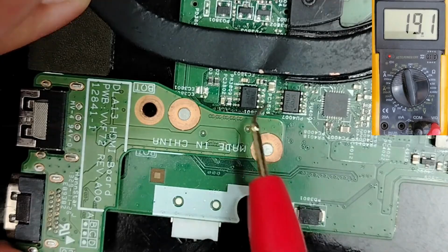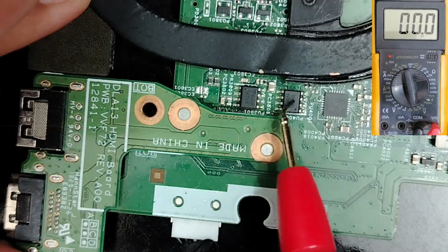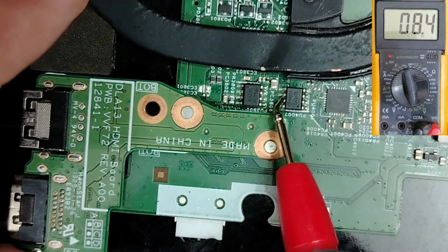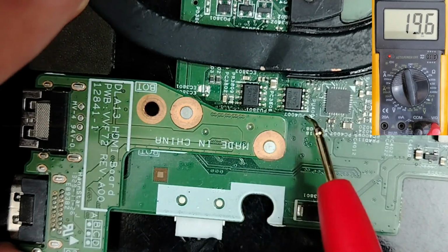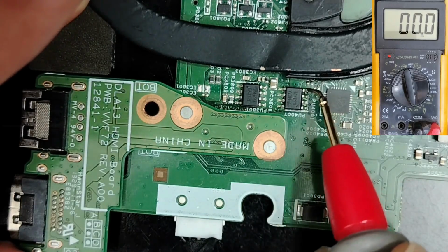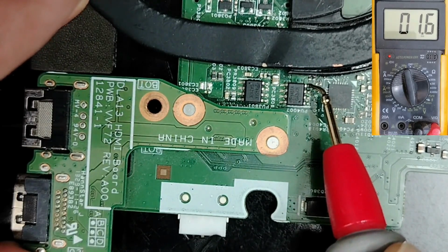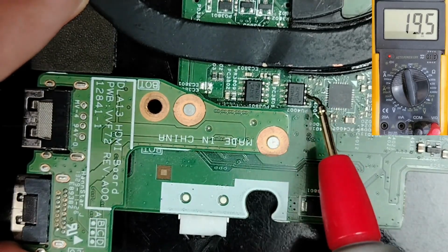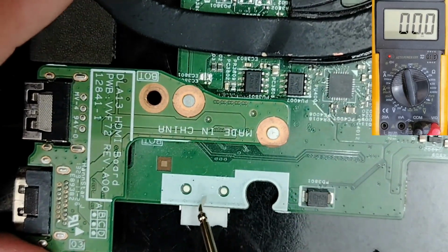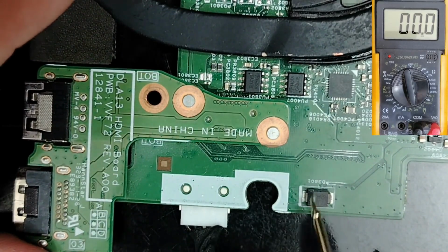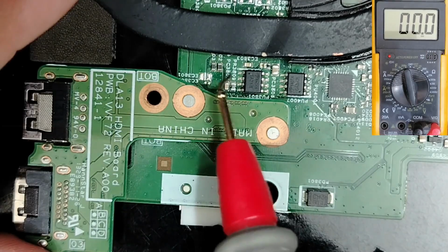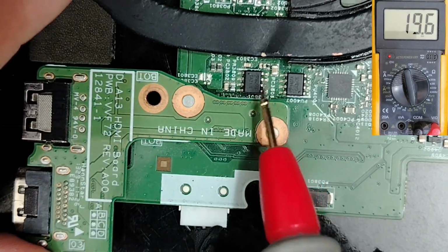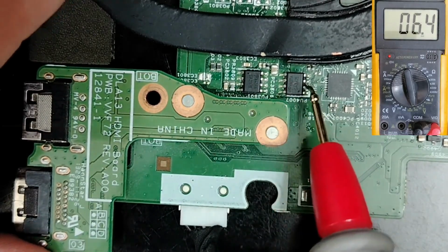Good. Then, as you can see, these two switches are connected together. Here we have the drain, here we have the drain. We will find 19 volts here. Here we have this point, which means this is the source. Here we have the gate. Let's check. We also have 1.6 as a control signal, which means we will find 19 volts here. So 19 volts travels from the power jack, passing through the protection diode, and then goes to the first MOSFET, and then to the other side, and then to the second switch, and then to this side.